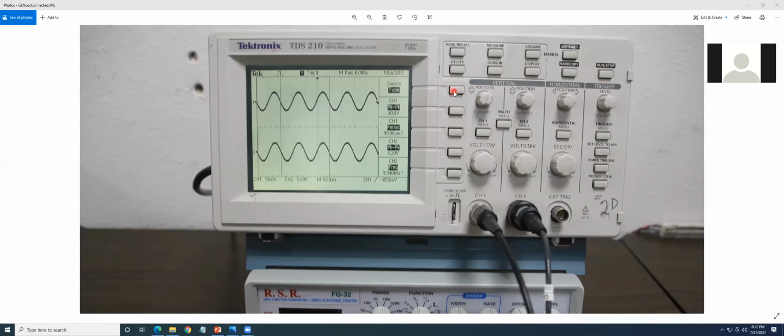Okay, then what? What else? Selecting the channel and pressing the button. When you press the knob, they will be displayed either source or the type. Which one do you want? Source. Okay, then you have to move this one to the source. Then you press this one to channel 1 or channel 2, whatever channel you want.